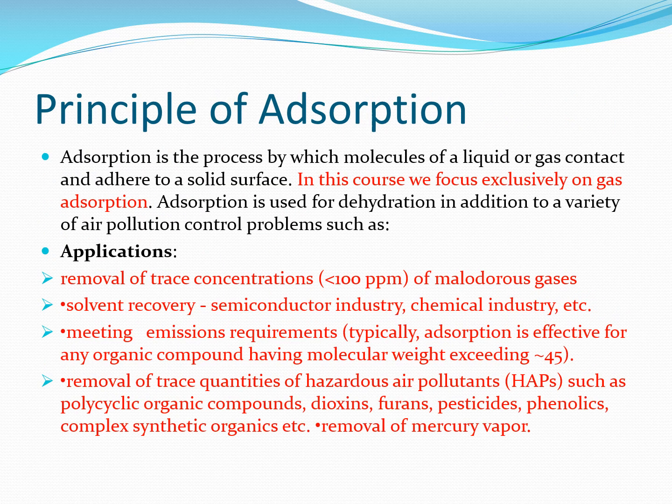So let us move towards the principle of adsorption. Mostly I have explained things, but we will see what is missing in this slide. Basically adsorption is a process in which molecules of liquid or gas adhere to a solid surface. We will focus exclusively on gas adsorption. Adsorption is used for dehydration in addition to a variety of air pollution control problems.